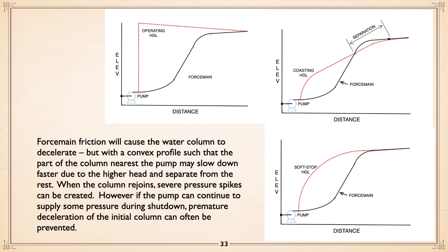That, assuming the pipe can take the vacuum, is no big deal. But then eventually that vacuum will stop the discharge to the right and suck it back, atmospheric pressure pushing it back, and you've got nothing between to damp, unless by some miracle you've got an air release valve that's brought in air. When those two ends hit, bang, you've got a real good spike and force mains get broken, and I have seen the results of that. Why did a municipality end up with about 5 or 6 breaks at one particular point on the line? Because that point was literally like this. It's almost to the peak, where you've got that situation, and the pumps were shutting down too quickly, and there you go.